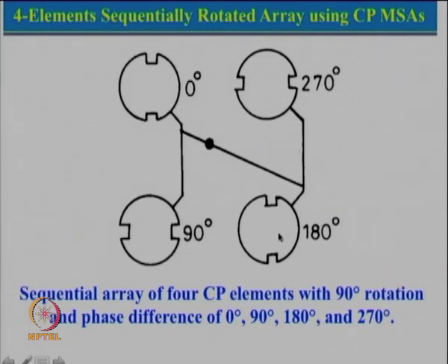Now, if you look at this here, this is symmetrical, this part is coming over here, this part is coming over here. So, we can say that this is that additional reference length here, and this one will be additional lambda by 4. Now, an additional 180 degree phase difference is obtained. So, whatever this length is has to be lambda by 2 plus this particular length, and if this is lambda by 2 plus this length, that would give us 180 degree additional phase shift.